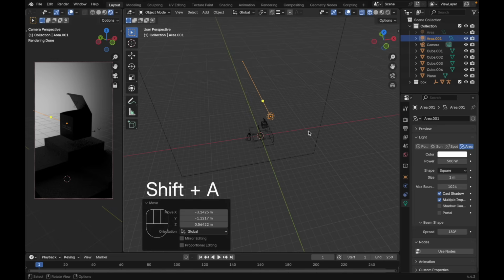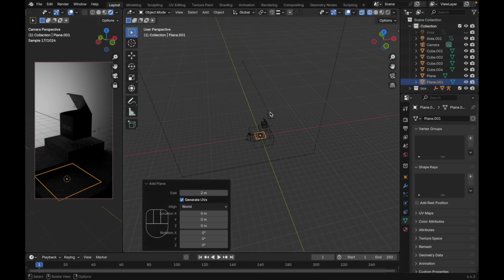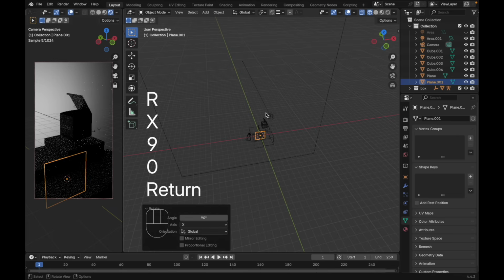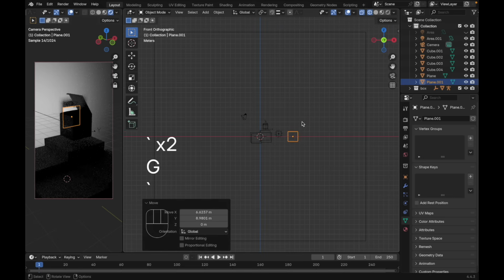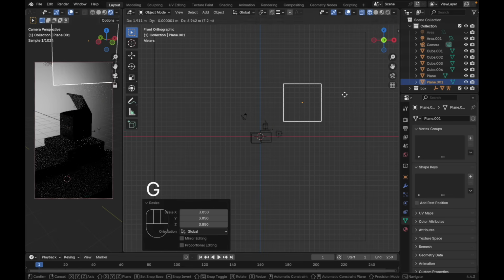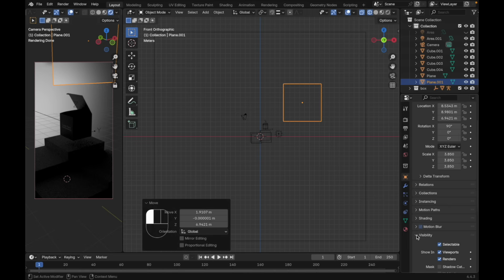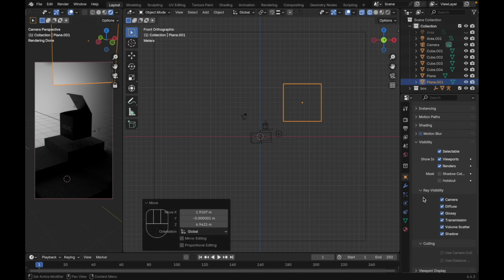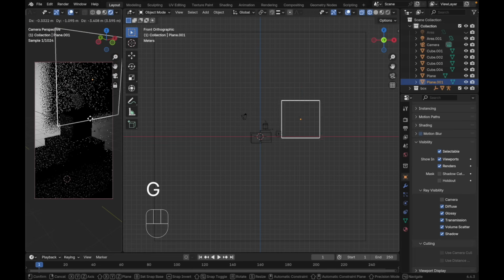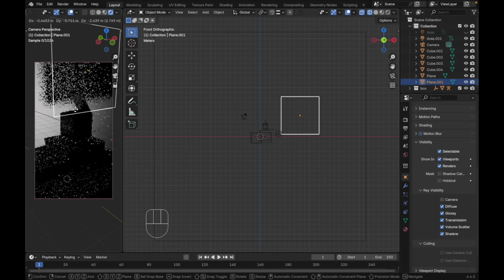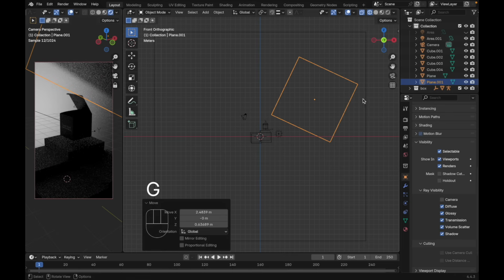We're gonna create the shadow. Shift A, mesh, add a plane, R X 90 degrees. Put your new plane here. Let's press S to scale it up, put it here. Then go to the object data property, visibility. I'm going to disable the camera, so the plane here doesn't show at the camera, it only shows the shadow. I'm going to rotate and put it somewhere like this.